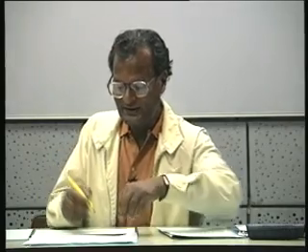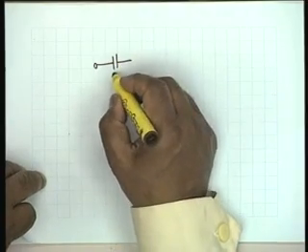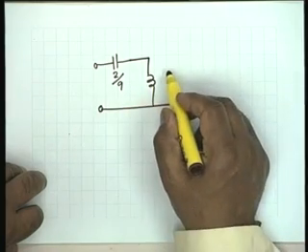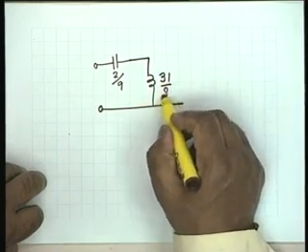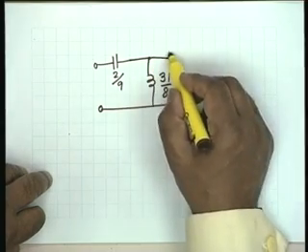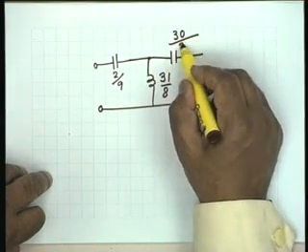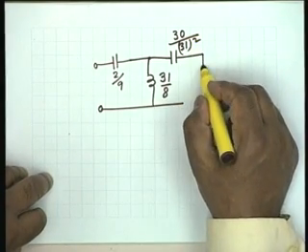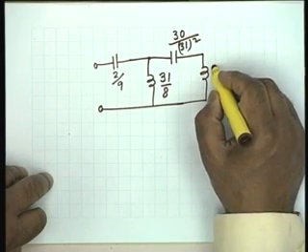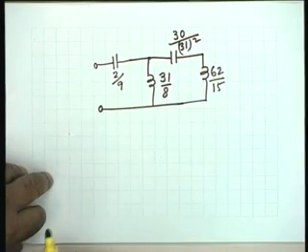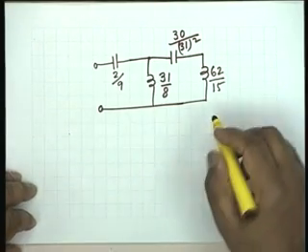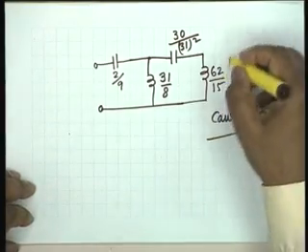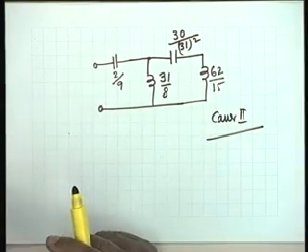So my final network becomes, we start with a capacitor 2 by 9, the next one is an inductor, value is 31 by 8, 1 by SL. The next one is a capacitor 30 by 31 squared, 961, okay, and the last one is an inductor 62 by 15, and that completes the job of cover 2. The rest is open circuit because the remainder is an admittance which is equal to 0.